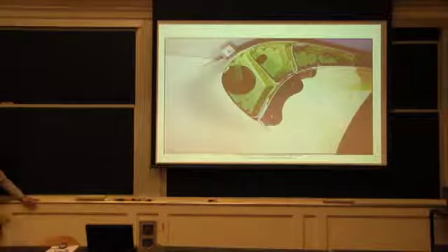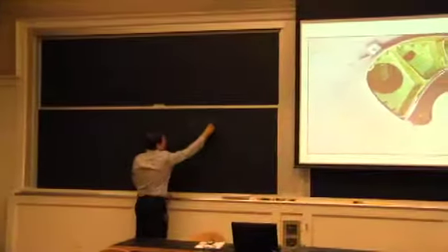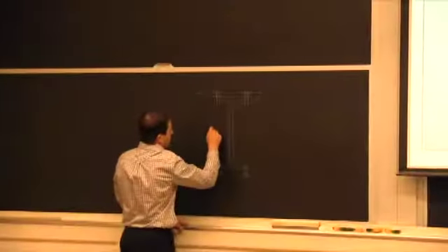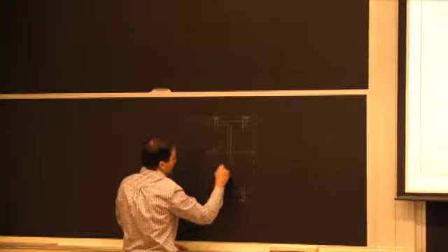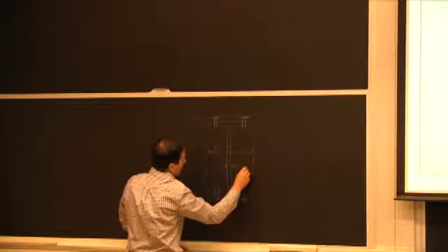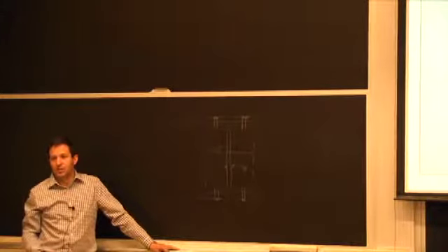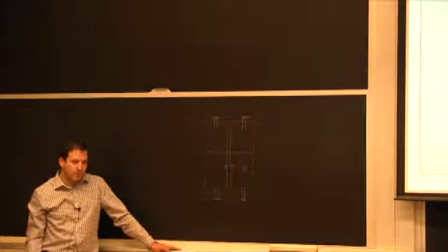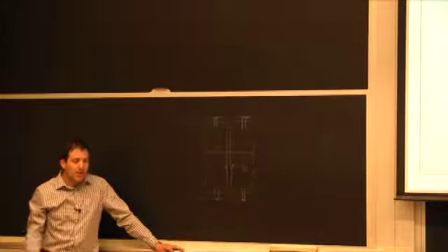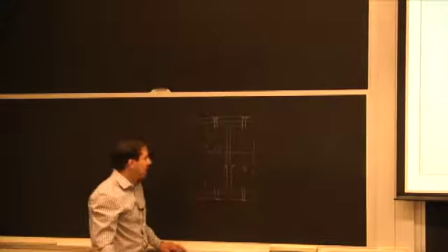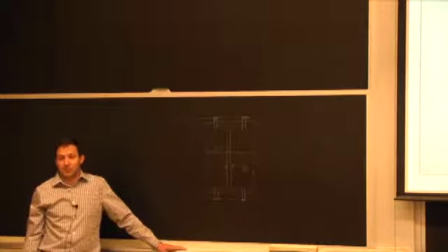So when we're talking about starting here from a plate that's 3.5 inch thick across, and then you end up, it's not to scale here, but it's only 1/8 of an inch. That's a lot of loss of material, and it's a very expensive process to go through in manufacturing. Titanium is difficult to machine. So as part of the optimization, again, the question was, can we make the same geometry but out of a casting? It would be awesome.